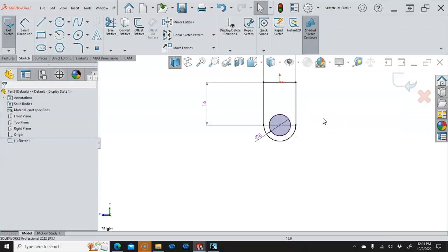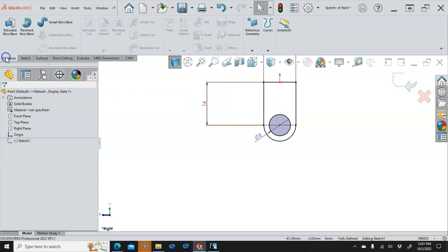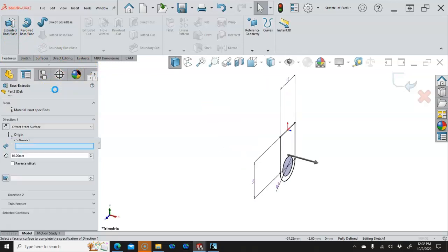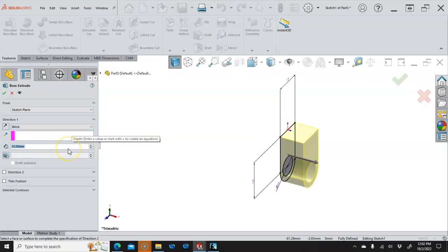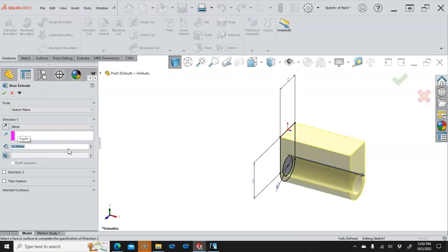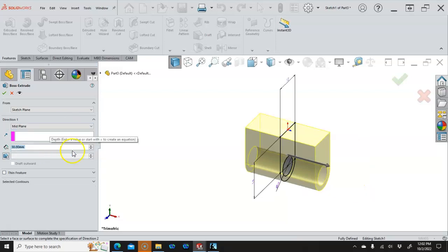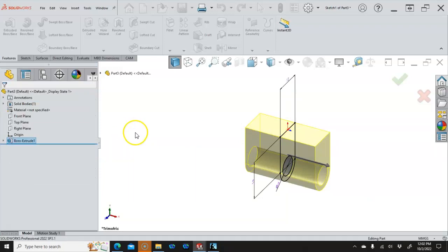All right, so this is going to speed things up a little bit. If I start using the S key and the numeric input, we're going to be able to follow that rhythm and go a little bit faster. So 30, and to use one of the other end conditions, let's go midplane. That'll keep the origin at the top center, and we can accept that.